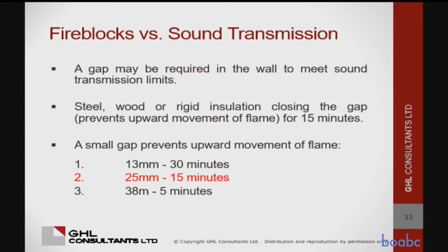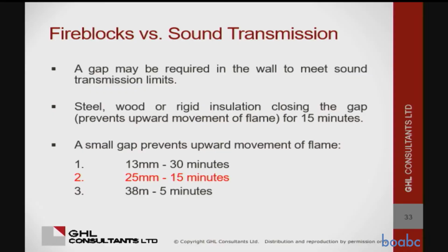So, we might need a gap in the wall for sound transmission. We're not talking about sound transmission, and maybe you'll look at our drawings and say, oh my God, that doesn't work for sound, but we're only talking about fire. But typically we get this gap up inside the wall for sound, and you can close the gap somewhere with wood or gypsum board or the steel fire stop thing, or the code says you can leave a 25 millimeter gap between two insulated studs, right?